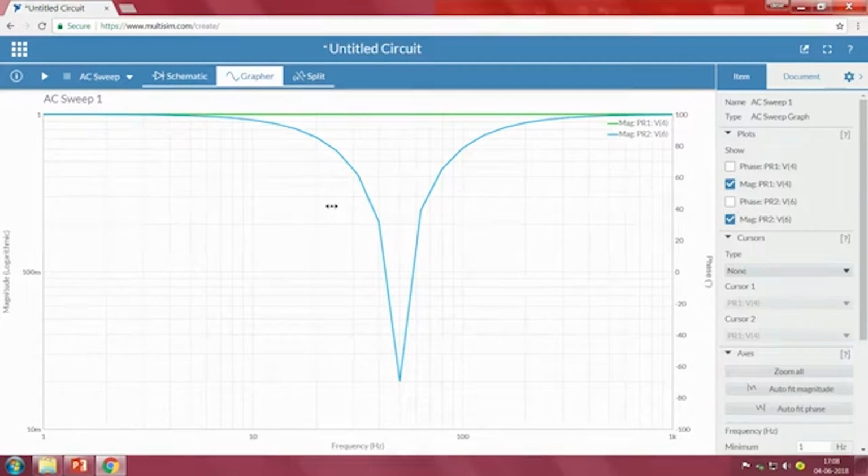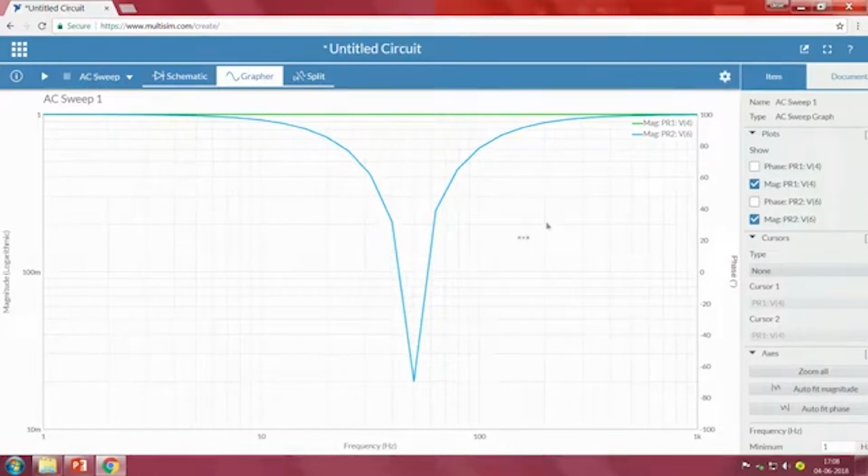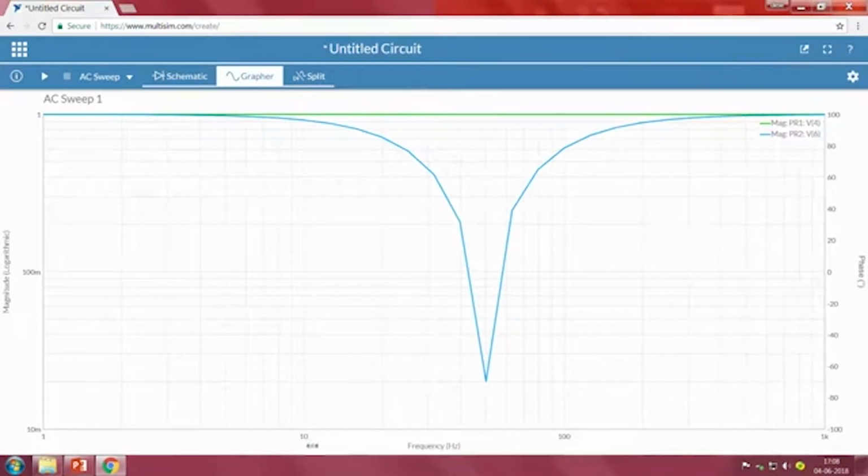Now, if we clearly see, this is 10, it is in a frequency domain. So, if you recall how we measure in a frequency domain, in a log scale basically 10, 20, 30, 40 and 50, right, 60, 70, 80, 90, 100. Now, when we see that, we need to know the 3 dB line, this 1, 2, 3, this point, right, the frequency at this particular amplitude is generally the cutoff frequency.